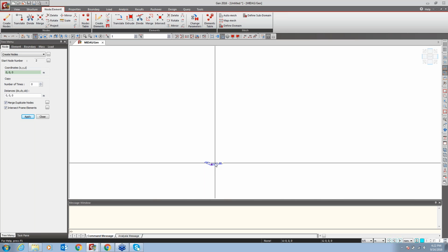The best option depends on the geometry, and it depends on the person also. Some of the consultants are much more familiar and comfortable with the AutoCAD DXF, because they know how to generate the center line plan. So based on that they will generate. But some of the consultants don't want to rely on the AutoCAD DXF, because if the joint between two lines is nearby or duplicate, then it will give an error.